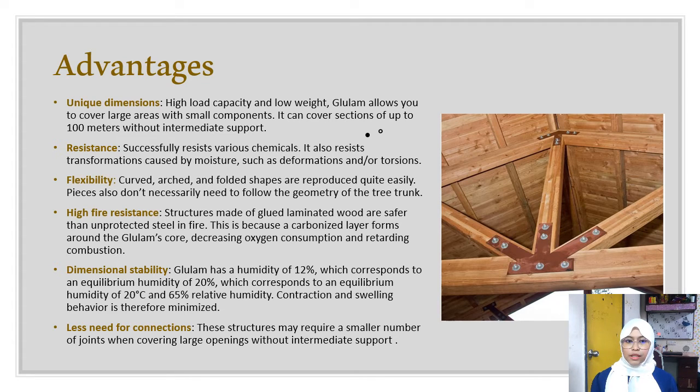Dimensional stability: Glulam has a humidity of 12%, which corresponds to an equilibrium humidity of 20 Celsius and 65% relative humidity. Contraction and swelling behavior is therefore minimized.